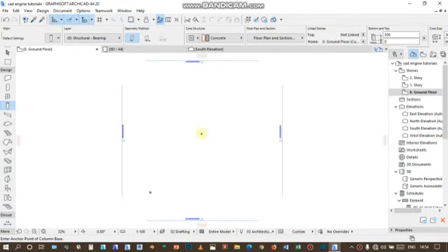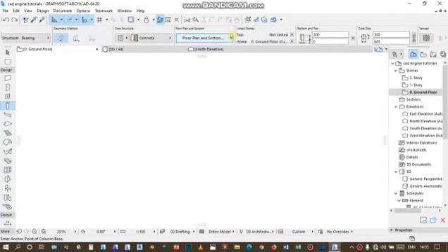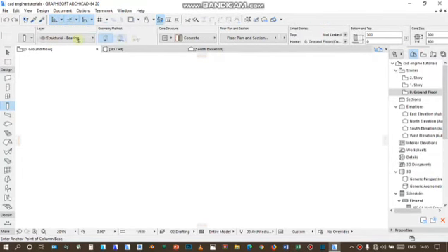Now hit OK. For the anchor point here, if you set this, it will now look at where it will be used. This is the meaning of the anchor point. Now if you put this one here, it will appear at the center. Now if you put this one here, it will appear this way. So this is how you set the column anchor point, for ease of construction, so that it can be placed well.